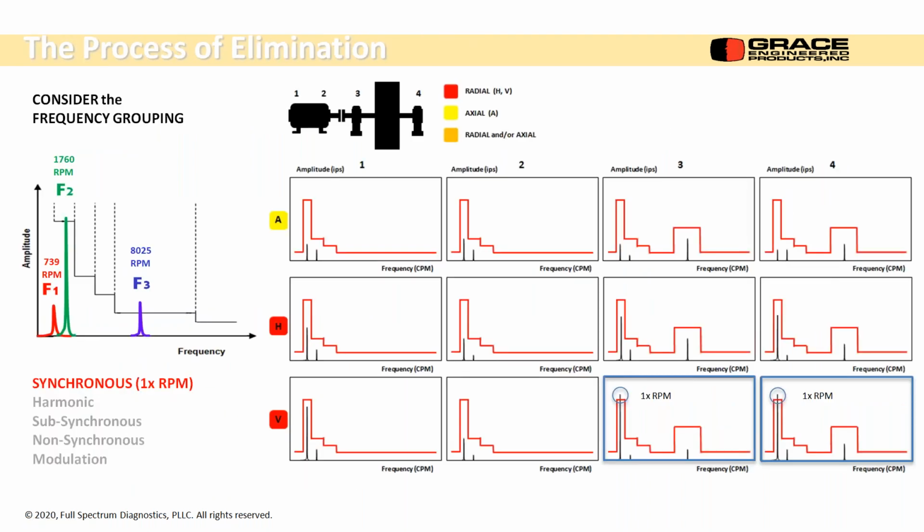This is how we would commonly take our data, and usually it goes into a database, and the database applies the alarms and tells us what's bad. And right now it would shoot out an alarm report that would say our 1 times RPM peak in position 3 on the shaft, so the fan bearing 3, fan bearing 4, they both exceed the criteria in the vertical direction on those 2 bearings. So that gives us some good information to go and hunt for what the problem is.